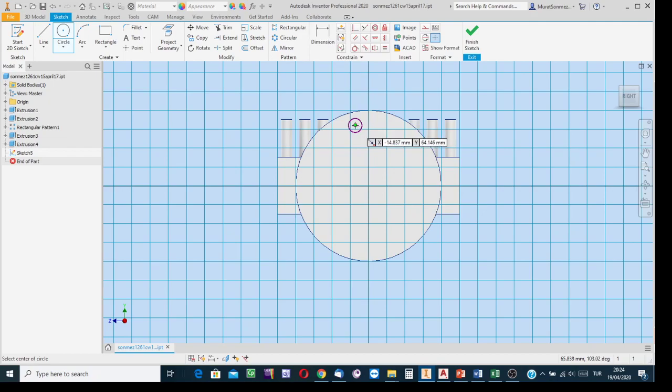The distance from the center to the center of this surface, say that is the radial coordinate. To be able to indicate the center of this surface, the projection process is needed. Apply Project Geometry to have the image of this boundary. This green line is the projection of the indicated edge. Its center can be snapped.